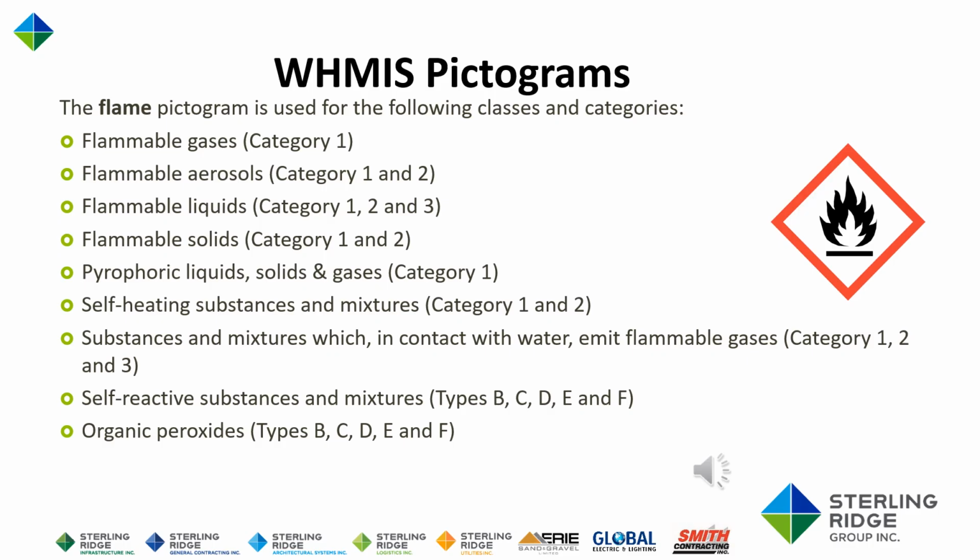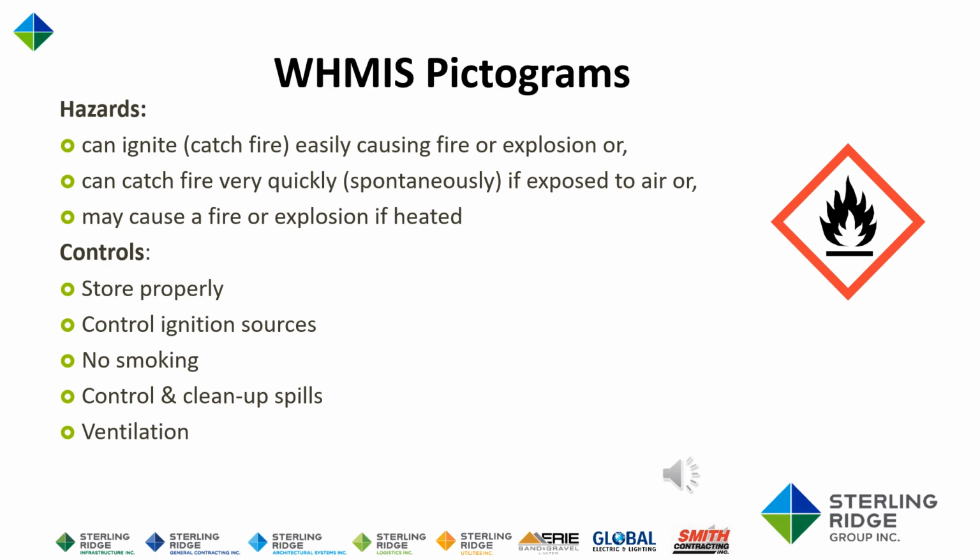Self-reactive substances and mixtures, Types B, C, D, E, and F. Organic peroxides, Types B, C, D, E, and F. Hazards: can ignite, catch fire, easily causing fire or explosion, or can catch fire very quickly, spontaneously, if exposed to air, or may cause a fire or explosion if heated. Controls: store properly, control ignition sources, no smoking, control and clean up spills.